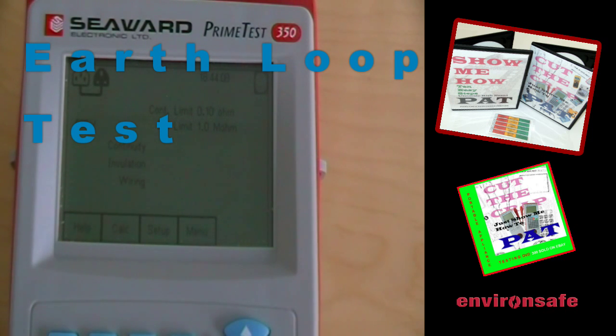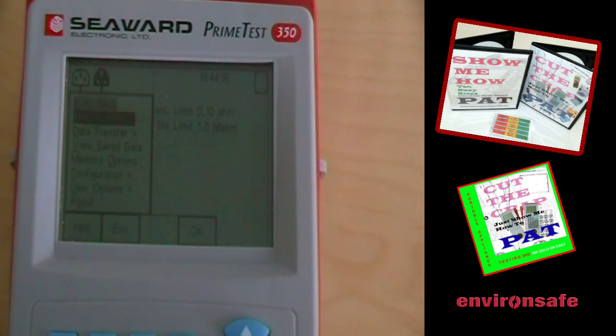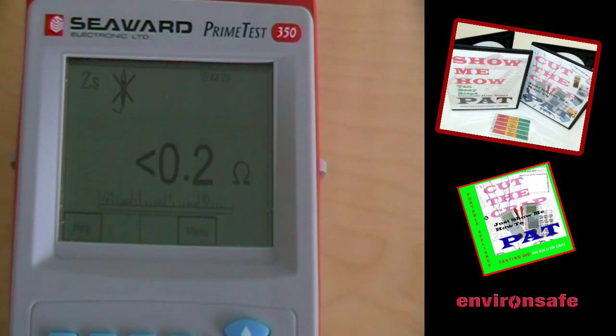How to conduct an earth loop test. F4 menu, scroll down to manual mode, F4 to OK, scroll down to earth loop, press F4 to OK, and press the green start button.